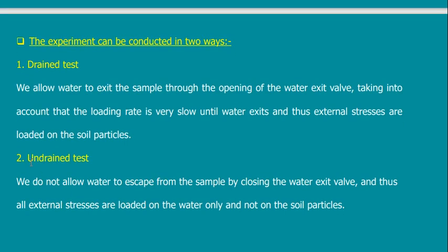The undrained, I just close the tap, that's all. We do not allow water to escape from the sample by closing the water exit valve, and thus the external stresses are loaded on the water only and not on the soil particles.